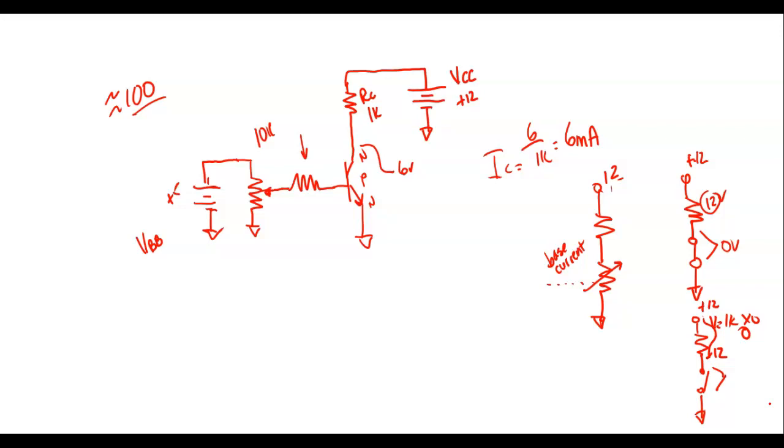Okay, guys, what size resistor do I need right here? I'm going to set this up to plus 5 volts to start off with, so I'm going to turn my pot all the way up. What size resistor would I think I would need right there? We're going to use a beta of 100. So IC equals to what? Beta equals to what?